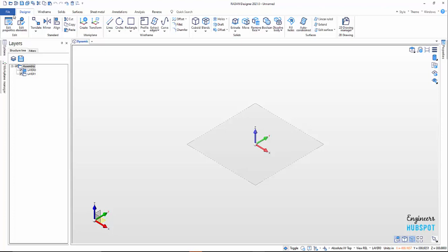This is where Designer steps in, and you can actually go ahead and prep your sheet metal parts here based on K factors, die width openings, setbacks. So you can do that all in here with Designer and get it to RADAN or wherever you need to get it to. So the first step here is you can draw and design in this.